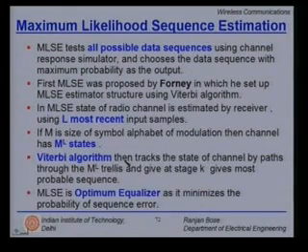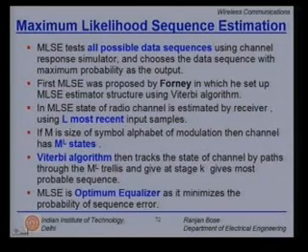MLSE is an optimum equalizer as it minimizes the probability of sequence error. Please note there are two things: one is the probability of sequence error and one is the minimum mean squared error. The bottom line is the probability of sequence error should be minimized. In earlier cases we said we will minimize the minimum mean squared error, and then it will automatically lead to a low probability of error. Here, for the first time, MLSE works on minimizing the probability of sequence error. So, in that sense it is an optimum equalizer.